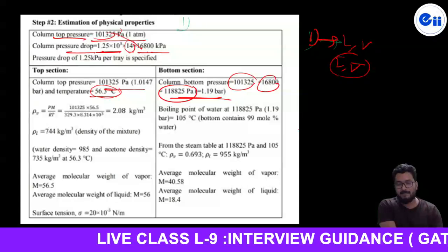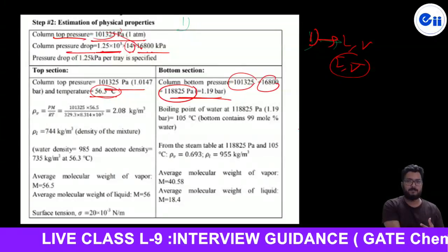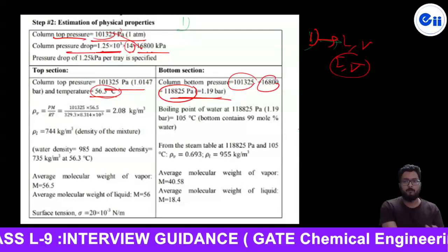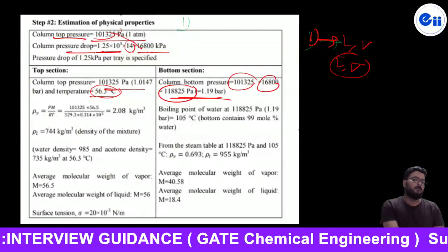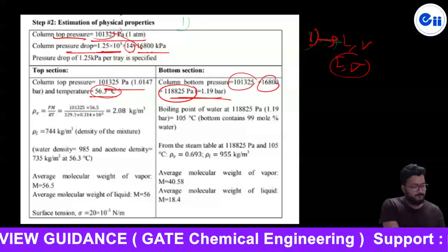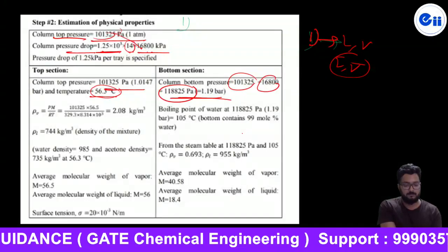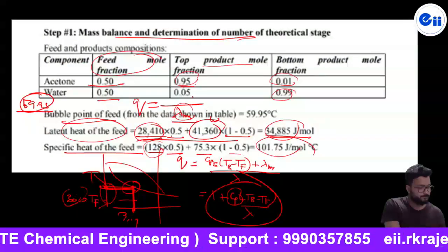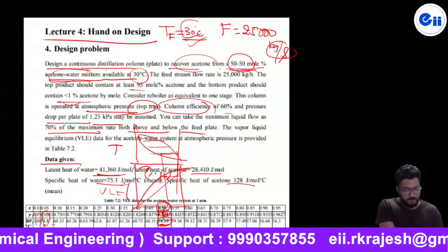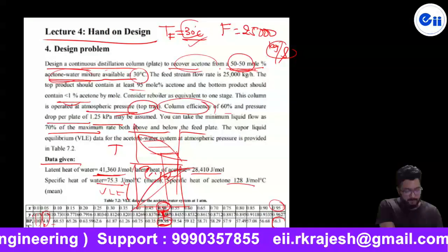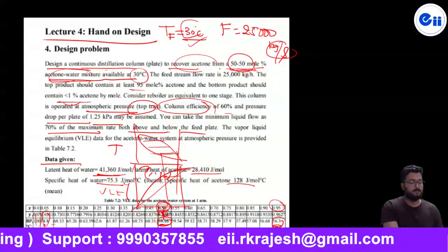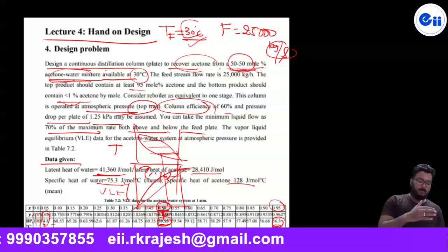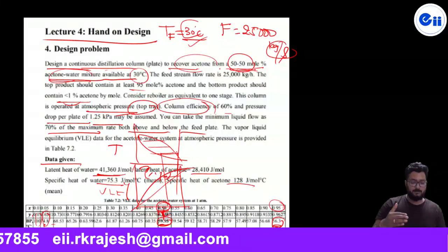ऊपर जो वेपर निकल रहा है that is 0.95 वेपर उसमें. तो since जो भी कंपोजिशन जा रहा है ऊपर वो भी क्या है 0.95 है. तो since it is 0.95 then obviously we can go for the corresponding bubble point temperature. Are you getting? तो ये जो डेटा आपको दिया हुआ था यहाँ से अगर देखोगे, ये देखिए 0.95 है, तो 0.95 जो bubble point temperature है वो 56.3 है. तो you are going to see as the purity increases the bubble point temperature goes on decreasing.